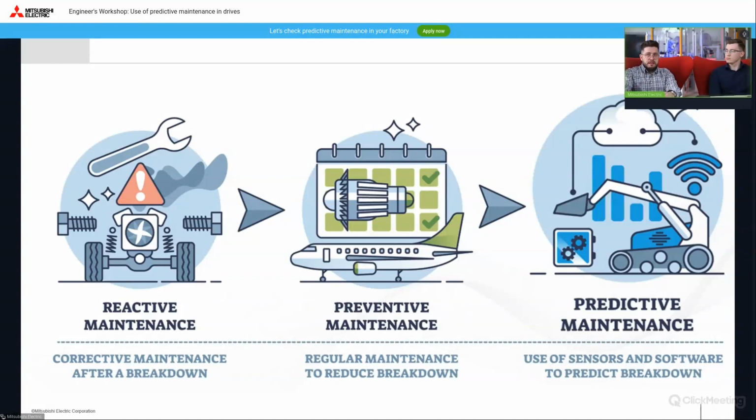The point is that in many cases, we can use additional physical phenomena to find out indirectly about the state of individual components. For example, analysis of vibration or oscillation in relation to bearing wear, analyzing current characteristics in a motor in relation to changes in friction or movement resistance, or, for example, increasing component temperature means increasing resistance to motion.